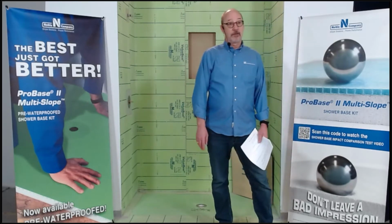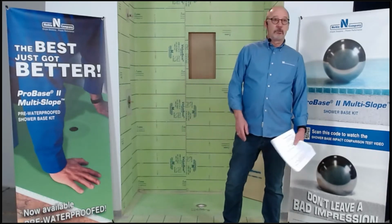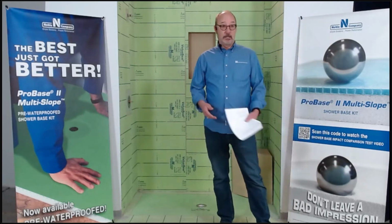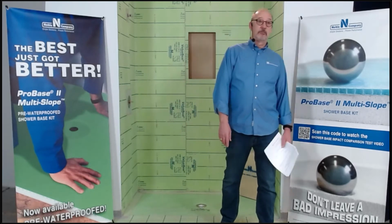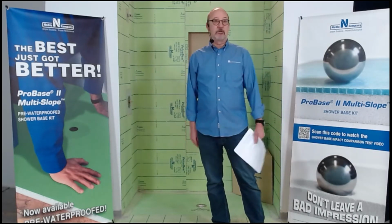Is the substrate flat, level? Are we dealing with a slab? Is the slab depressed? Are there certain requirements or locations that need to be met for the drain? What type of drain is it? A point drain, a linear drain, a clamping style drain? Maybe it's a bonding flange drain. What membrane are we going to be using? An A118.10 surface applied membrane or a PVC or CPE type of shower pan liner?